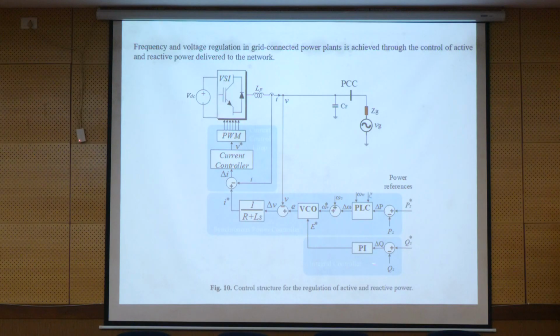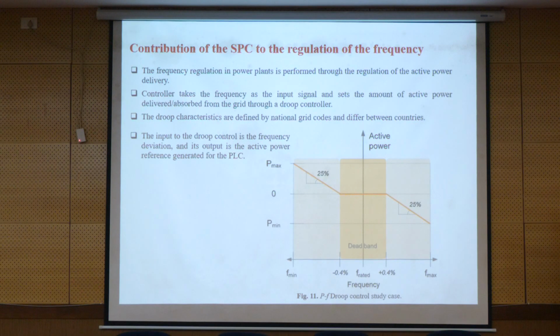Then we also have this part, which in the conventional method was the IQ and I reference, then a PI controller, to control the system. So up to here, active and reactive power can be compensated, and voltage and frequency can also be regulated. Now we are going to discuss the contribution of the SPC to the regulation of the frequency.